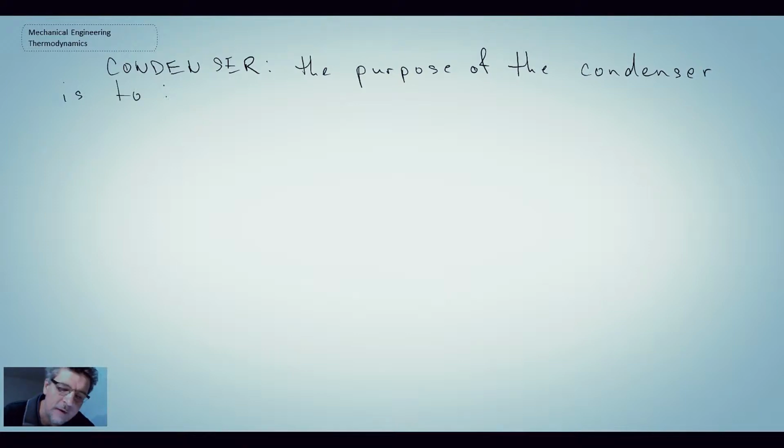So the purpose of the condenser, there are actually a number of different purposes. One of them is we want the condenser to be operating at a low pressure, and that is the pressure at which we expand the steam in the turbine to.